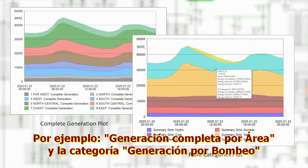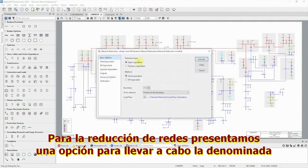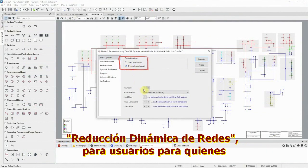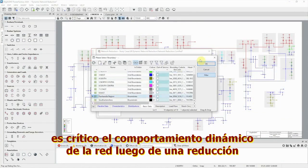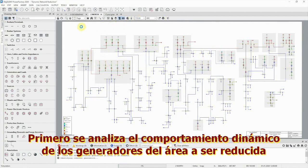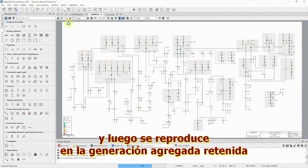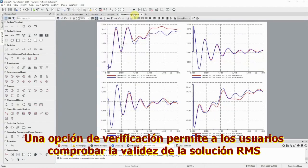generation by plant category. For the network reduction, we have introduced an option to carry out a so-called dynamic network reduction for users for whom the dynamic behavior of the network after reduction is critical. The dynamic behavior of the generators in the area to be reduced is first analyzed and then reproduced in retained aggregated generation. A verification option allows users to check the validity of the RMS solution.